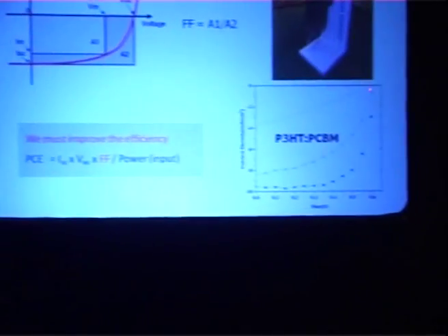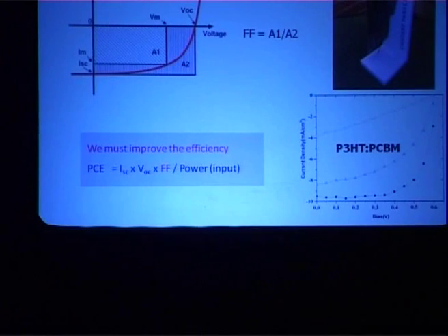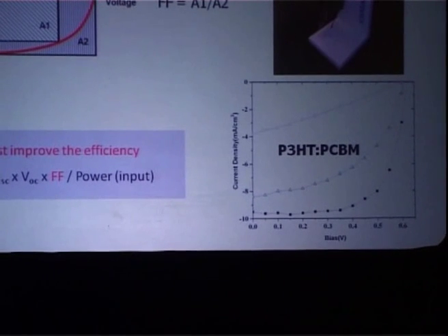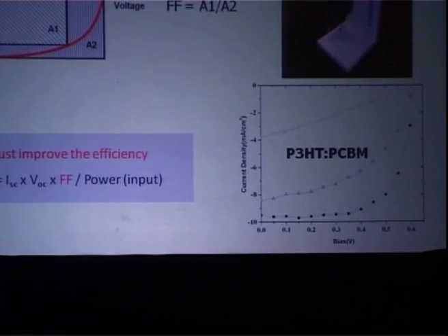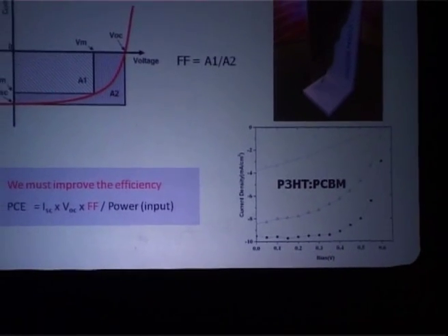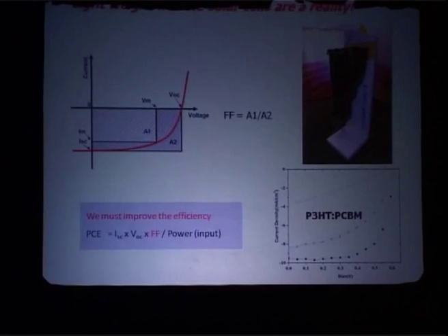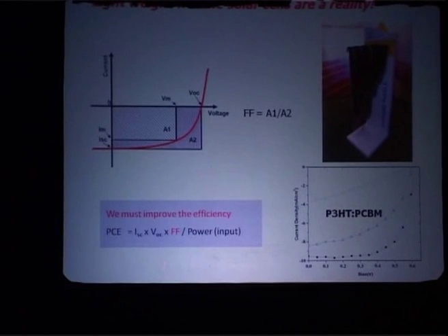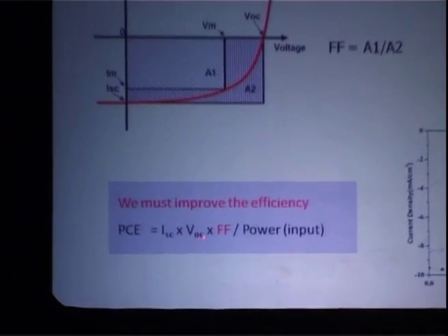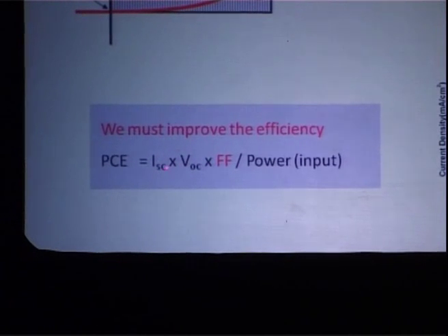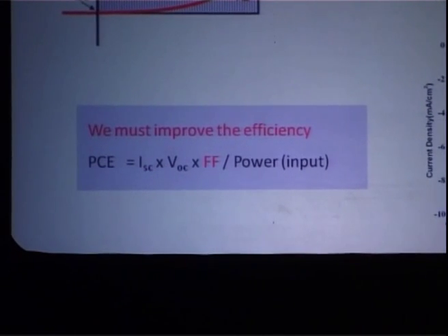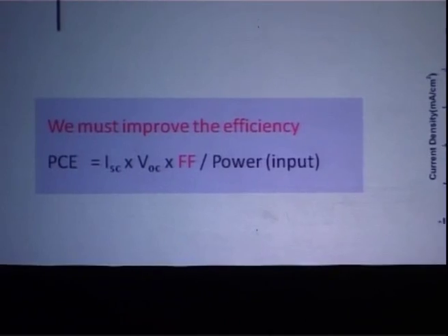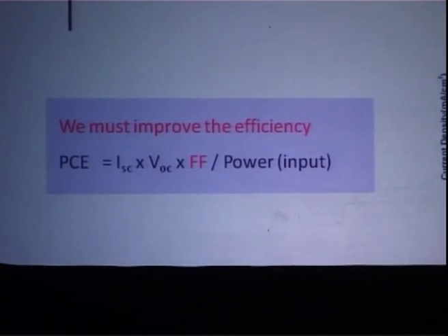In this case, and for good fundamental reasons, the open circuit voltage is much more fundamental. It's related to the electronic structure. The current is basically related to the morphology. If I have a very poor phase separation and I don't have good connectivity in those networks, then the current will be pretty low. So these are the kinds of things. This is what I would call fundamental parameter. The current has a lot to do with materials science and morphology, and the fill factor is dominated by recombination physics that I'll come back to.